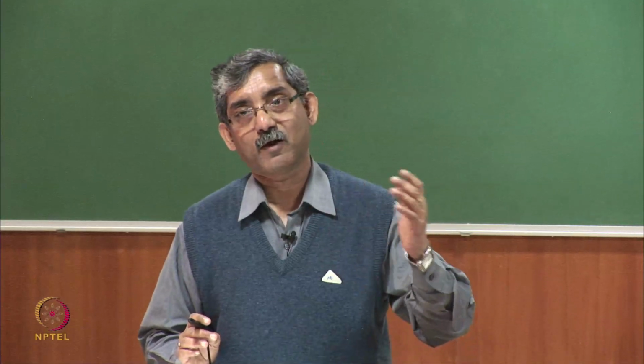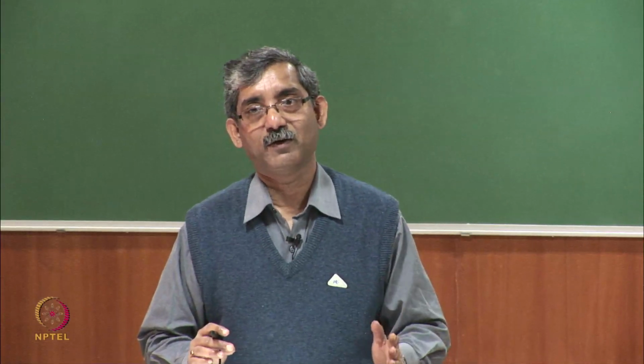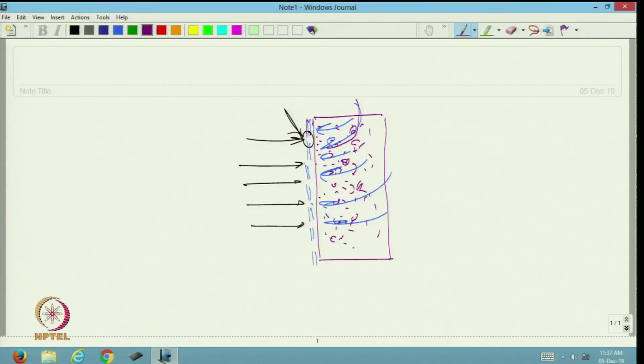Like in air filtration we have discussed surface filter like cake filtration, a similar thing happens here. Initially, through these pores, the smaller soil particles will come out. After putting the geotextile for a few days, you can see the smaller soil particles will keep coming. This is called piping, leaving the particles with larger diameter.